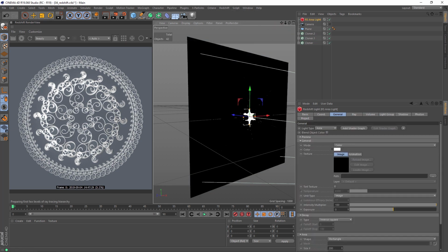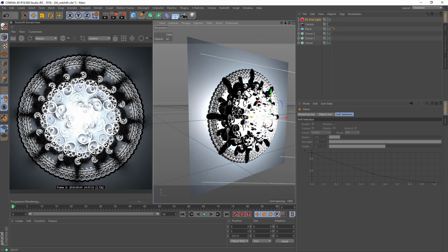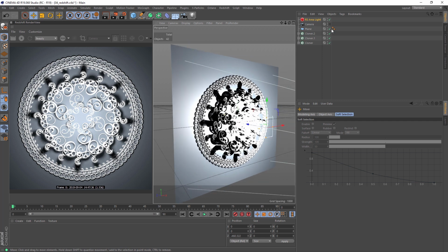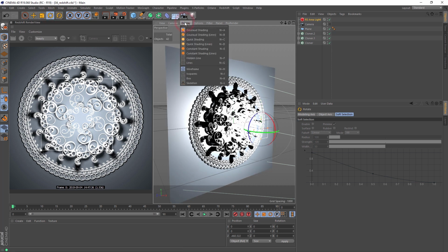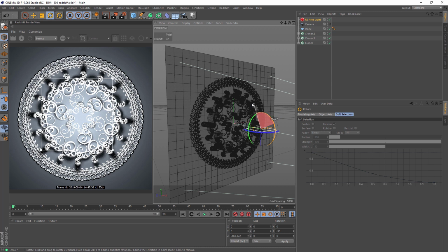I use an area light. As I said, we'll use one light, and we immediately get an update and struggle with the viewport. So I pause this thing, rotate, go to display, disable shadows, and go to hidden line mode. We have a speed increase.